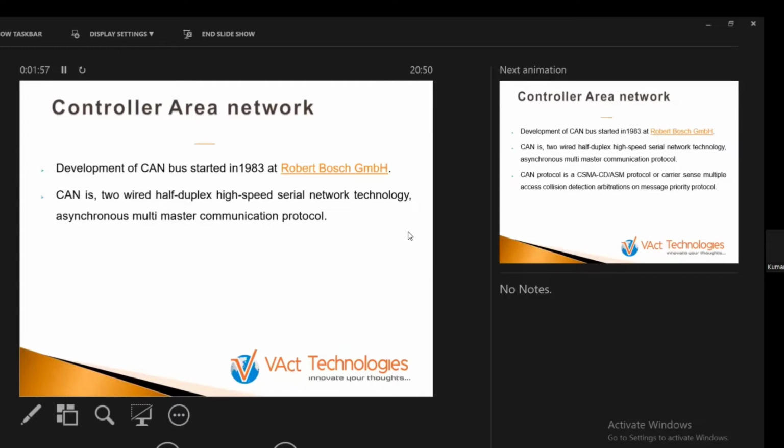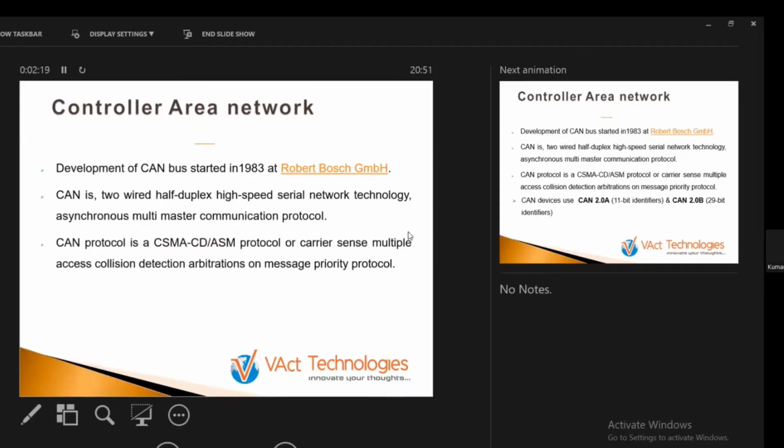It's also a multi-master communication. Nobody is the master here. Every ECU we call a node. Anybody connected to the CAN bus is called a node. Every node thinks, I am the master. Nobody is a slave here. So it is a multi-master communication protocol.